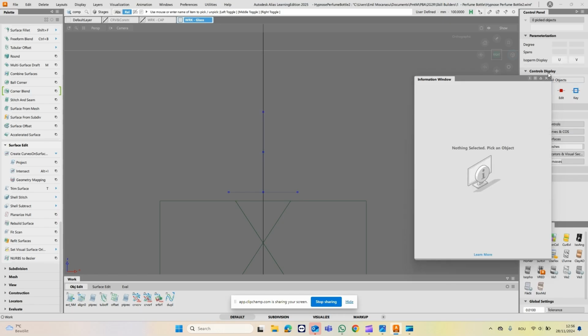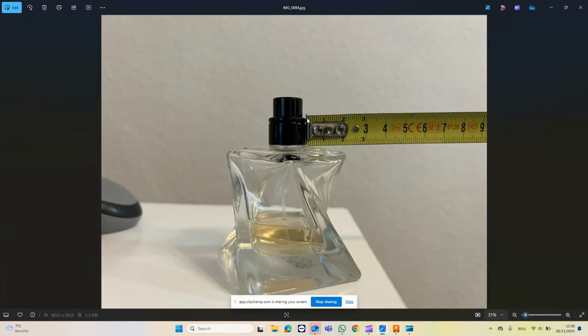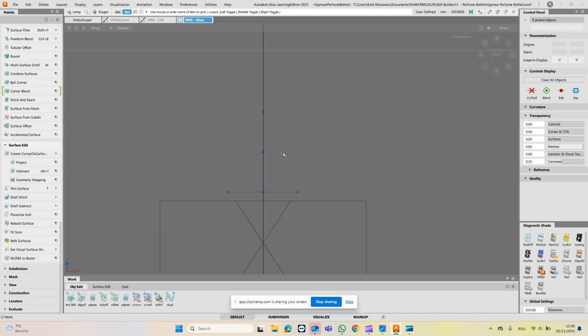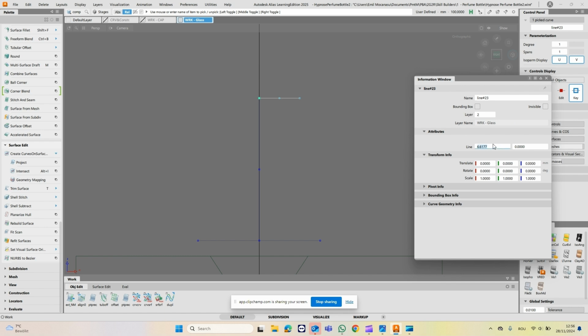I'm trying to get the proportions right. And we've set 2.5, that gives us 15 at the top there from the 20. So if I go only half of that, that's 7.5 millimeters. So Control, snap it there. With the middle mouse button, I went to the side, pick the curve, and go here, 7.5.